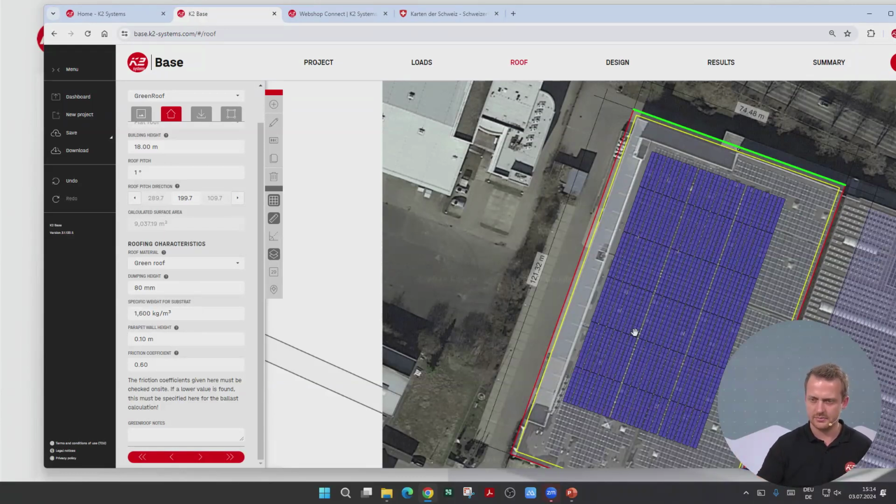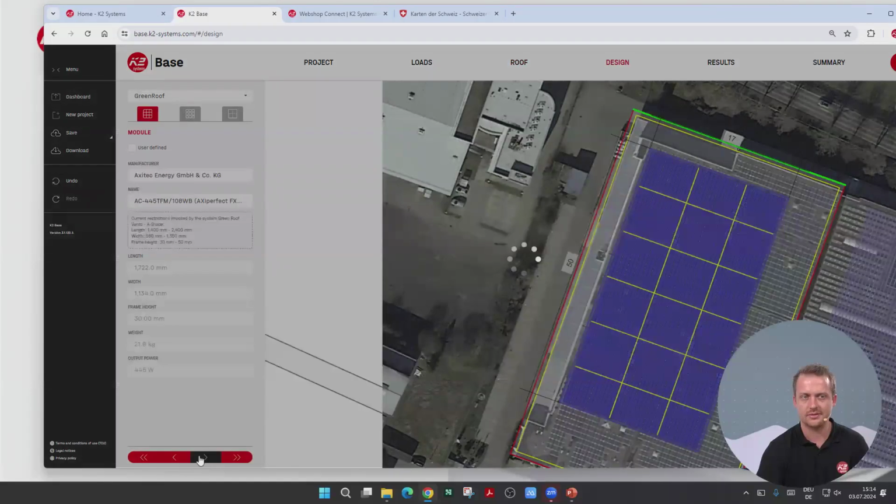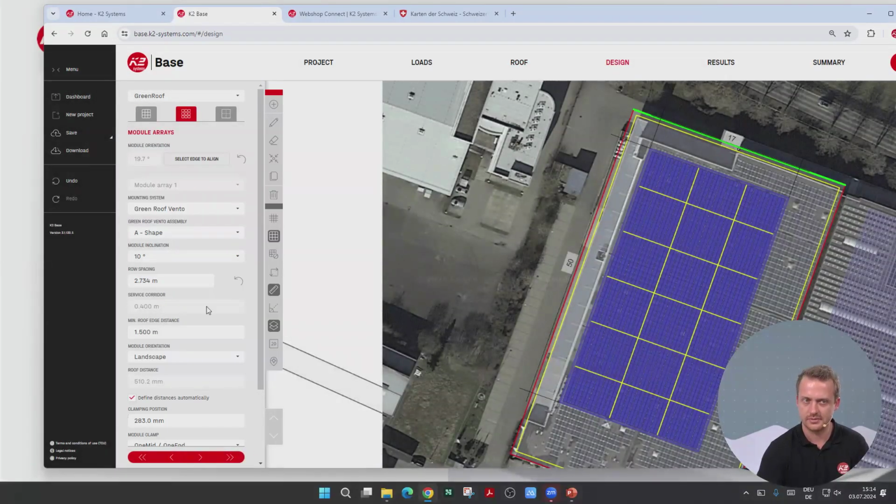Correctly ballasted. But I think we really need to stress that actually, Basti, because this acts as our ballast. Yeah. So if you have made an assumption about it and this assumption is wrong, this could be very dangerous in the future. So if you have assumed something and then you go and change the product, please recalculate the system before doing the installation.